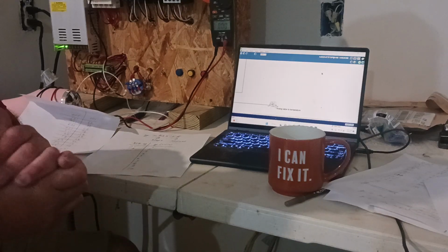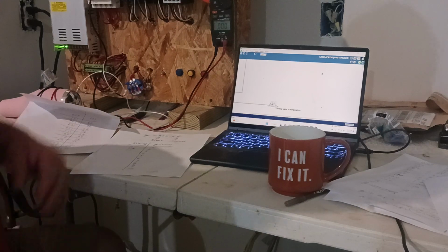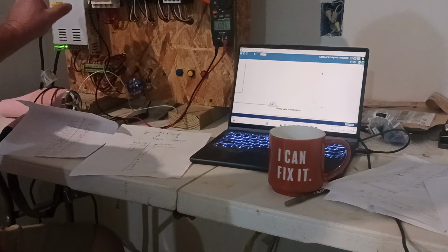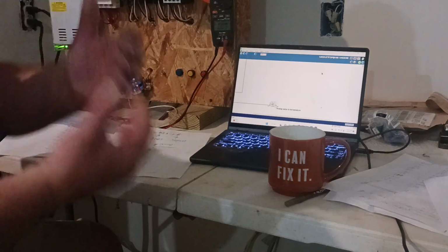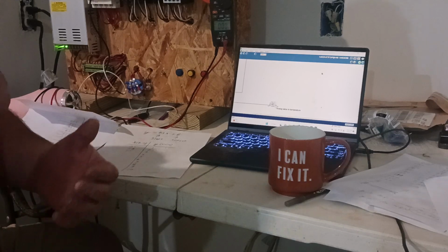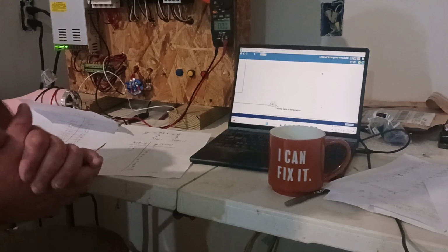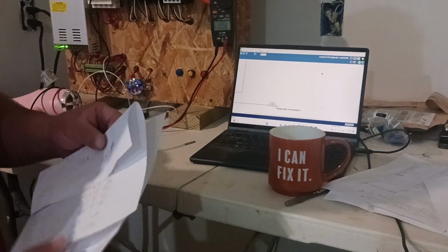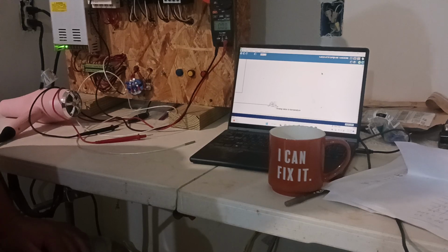Unless you're a math whiz or a math teacher, that may or may not make much sense. Just know that there is a scaling process so that we can apply an analog signal to a PLC. It gets a certain number that may not make sense to you, but then there's scaling so we can turn it into a value that makes sense, whether we want to know the voltage being applied, or the temperature or the pressure or something. I may not have been the greatest teacher at that. It's kind of a complex thing to teach, even though it's actually fairly simple. It's just hard to find the words to convey clearly. But hopefully you can kind of see how analog works.